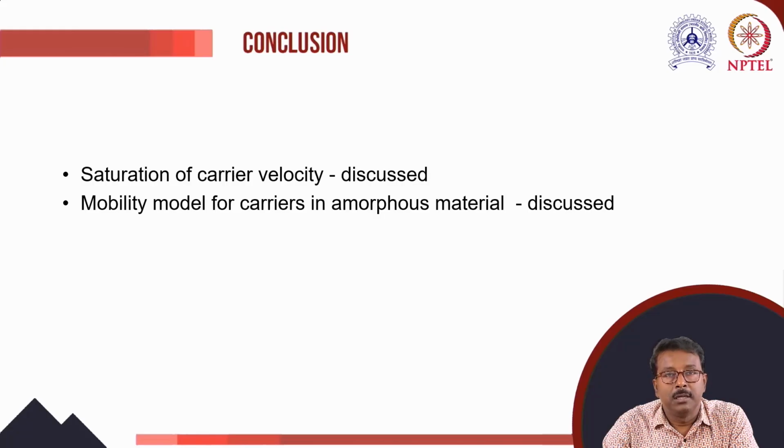All these things may be combined also. To determine the mobility for these amorphous type materials, we have to consider the distribution of trap states or tail states. If we consider a Gaussian distribution, then the Gaussian distribution model will be used, mainly for organic semiconductors.